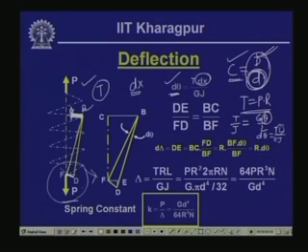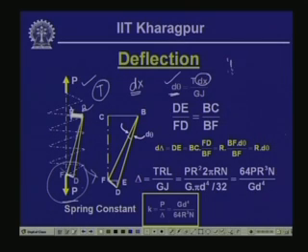Now, this distance Fd can be written as BF times d theta. If we take the components of this Fd, we will have a horizontal component and a vertical component. This particular spring, where we have considered one segment, is producing one horizontal component. Since the spring will have a number of coils, and this horizontal component will be produced by each of these segments, the horizontal components at diametrically opposite points in the spring will cancel out.